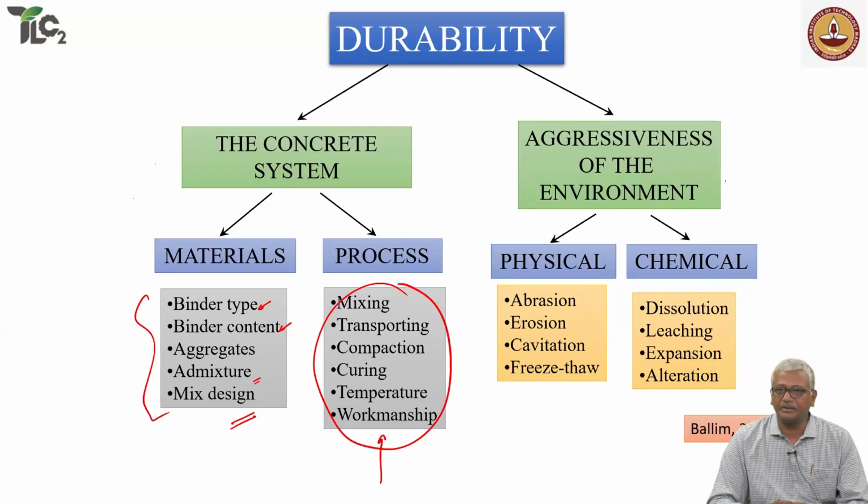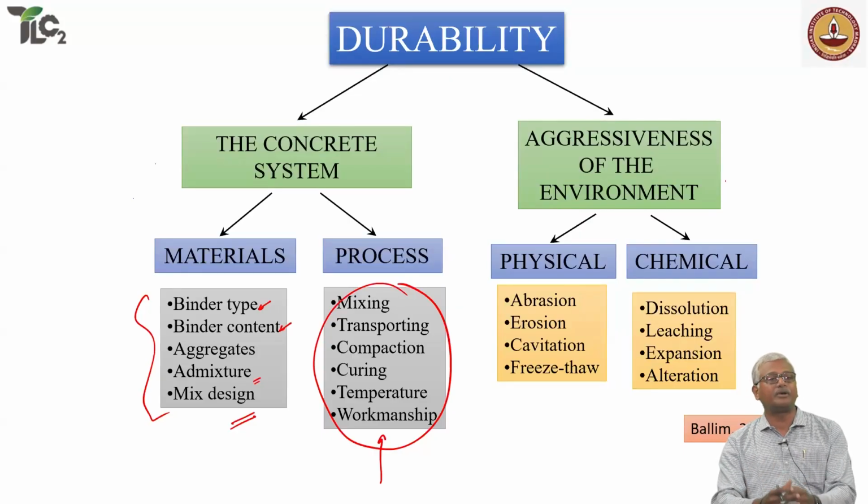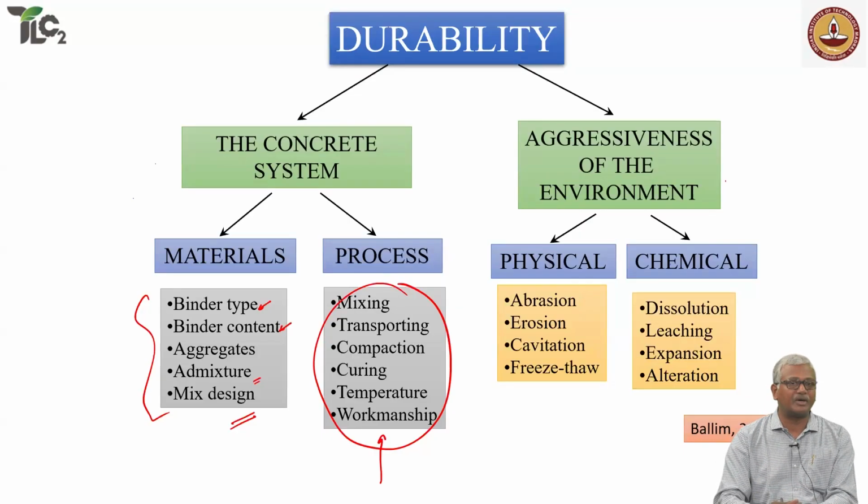Humidity, right? Because humidity affects various other processes. It's not a direct deteriorating factor, but yes, it affects other processes. The temperature, high temperature in some instances, could lead to some volumetric changes that lead to further cracking. That's mostly at the early stages. Yes, all of these things affect the quality of concrete as it performs in a given environment.